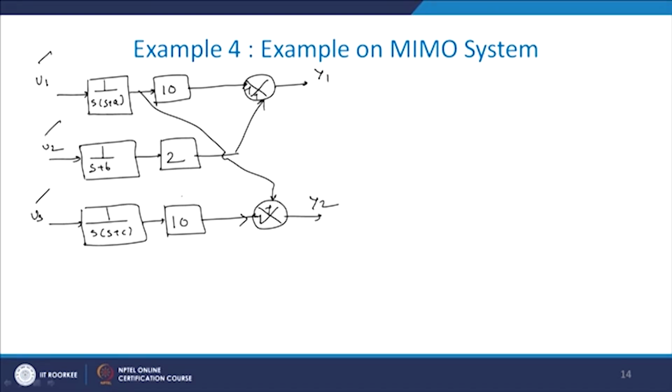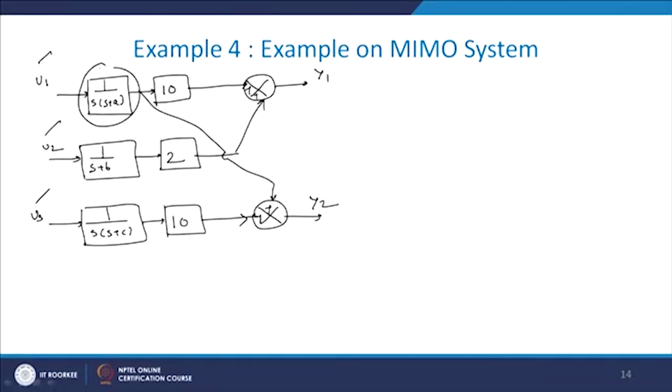Now we have to solve this problem. Definitely, one integrator means we have one state; if there are 2 integrators, there are 2 states. So we will find that if you separate this equation, just now we have seen the last example. So it is possible that we can simplify this part and easily get the state space model. So how to do it? Here I am rewriting the block diagram again.